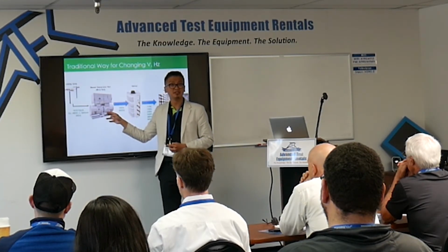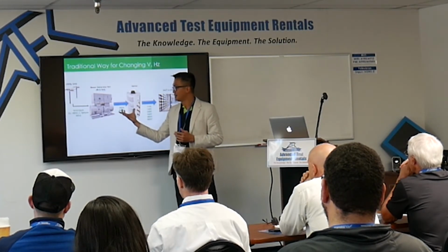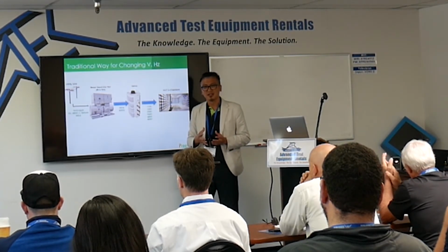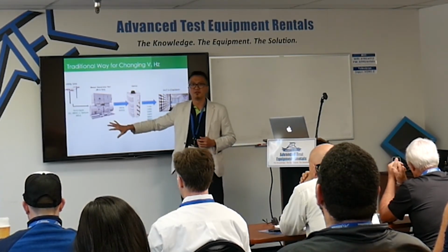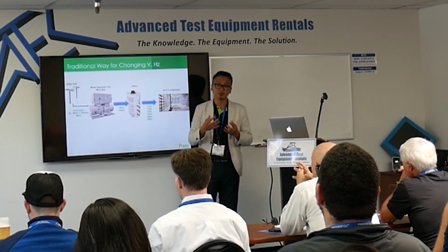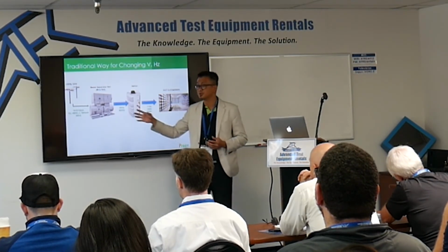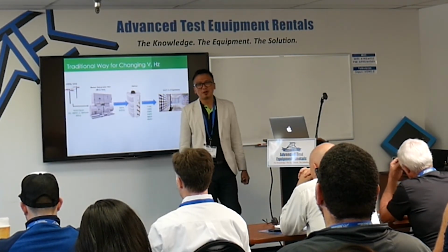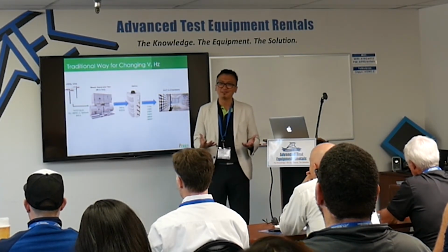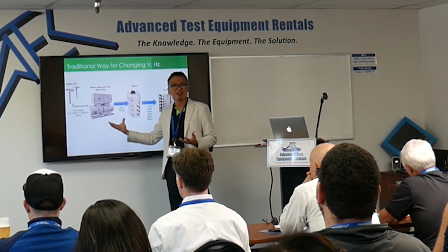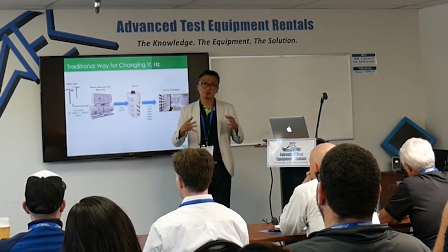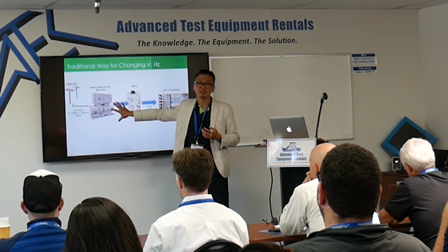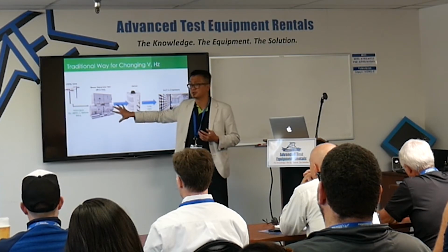You use a motor generator. If you are working in a testing lab, maybe you see this, maybe not, because this depends on the facility size. If they are trying to change the voltage or the frequency, they will use this way. You think, why is it so stupid? Why don't they just buy a switching power supply? It is too expensive. Nobody can afford that for like 100 kVA. If you buy a power supply for this, it's too expensive. This is very cheap and very low cost. And if they only need to change the voltage and frequency, they will do it this way.